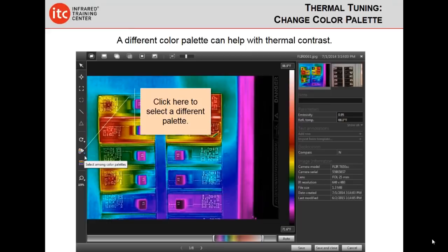But first, inspection frequency that was asked about for PV sites. It just varies, and the reason I'm saying that is it varies by age. Of course, one that's a little bit older, it might be something you want to do every quarter. Of course, there'll be other ways of measuring productivity. It isn't going to be from the air. This can also be measured by devices that are attached to the unit. But what we're seeing is about once a quarter, depending on age. If they're newer, once every 6 months. So that's what I'm seeing from people that attend our course.